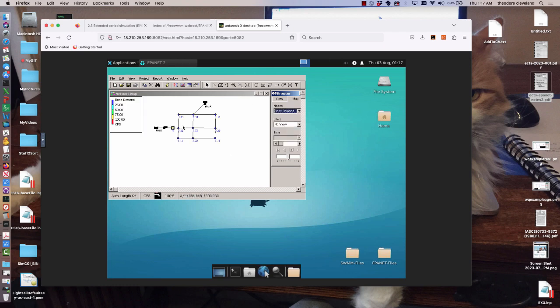Then at each node we have base demands. So we have non-zero demands everywhere. So we expect, if this reservoir elevation is maintained at 315, that is enough for gravity flow. The pump won't run very much. Let's go ahead and run the simulation. It has a single period simulation.